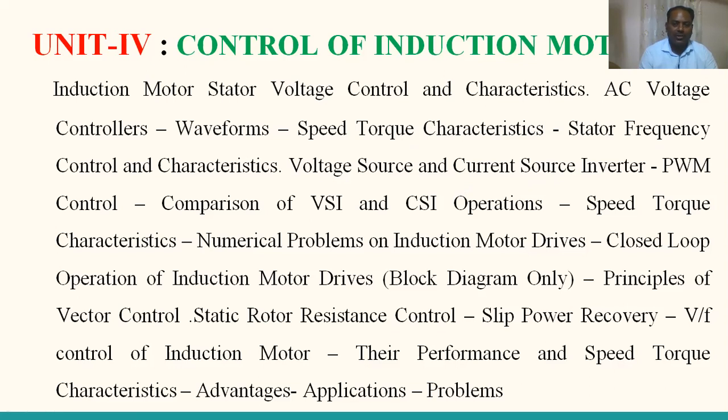The voltage source inverters and current source inverters are going to be analyzed here, which is a better option for quality speed control with the help of the V by F control method. Similarly, rotor side control is exclusively possible for the slip ring induction motor, such as static rotor resistance control and slip power recovery scheme.